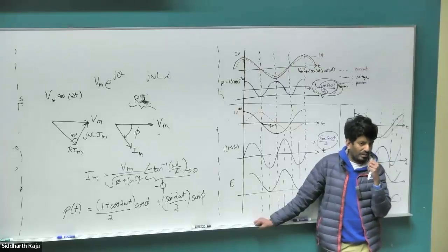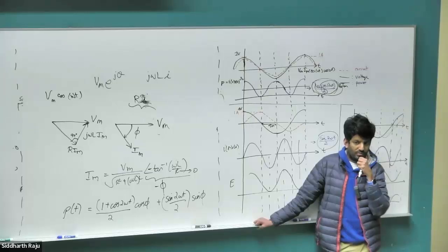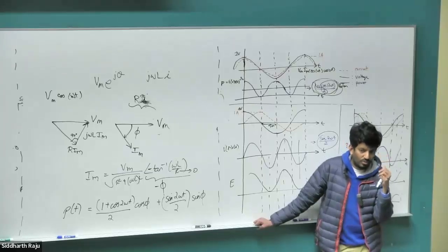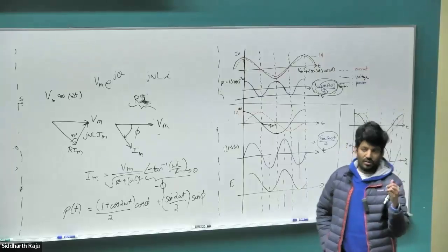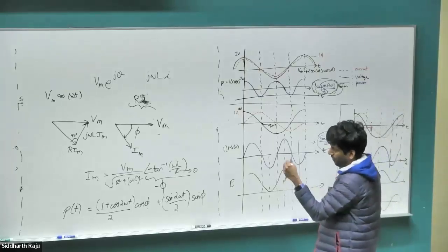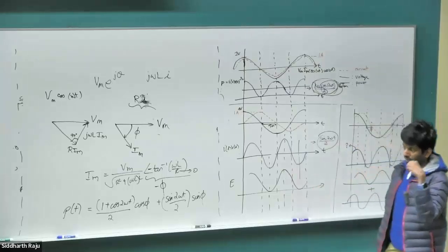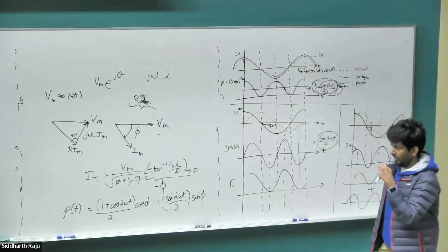What does that current do? That increased current, what will it do to the voltage? It also phase shifts all the voltages in the network, and causes a reduction in the voltage magnitude. Your voltage starts to droop, right? When you have more and more reactive power, you end up taking more current to get the same amount of energy into your load.